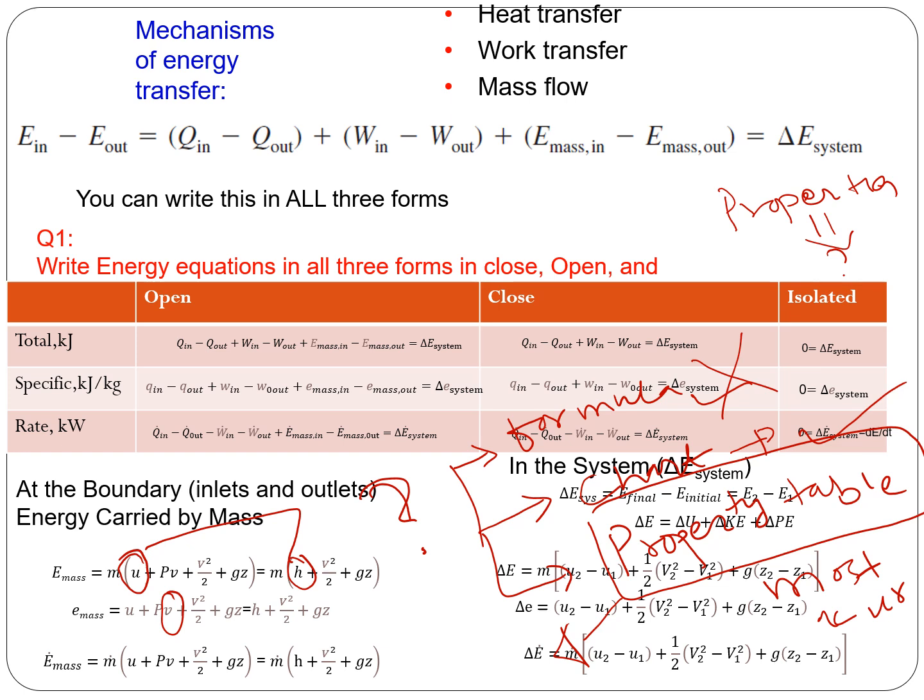And in order to apply the laws of thermodynamics, if you think about the first law of thermodynamics, we need to know the value of property. The property could be internal energy, enthalpy, or specific volume. So this value needs to be known. So how do you find those values? These are the three possible ways, and the most reliable and the most accurate method is using the property table, and that's what this chapter is focused on. Okay, that's the motivation of this chapter.